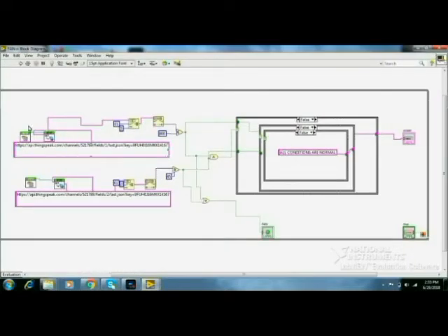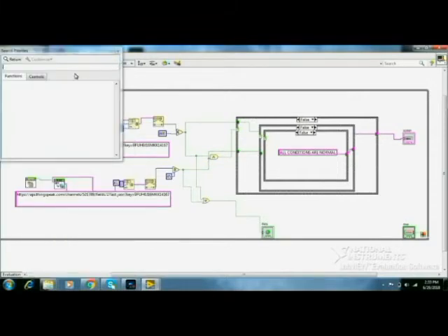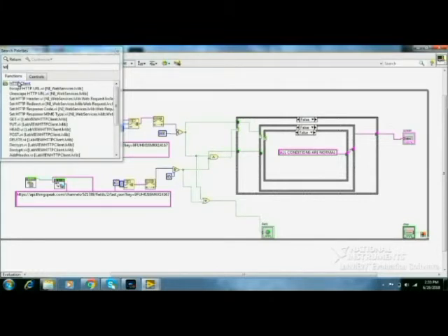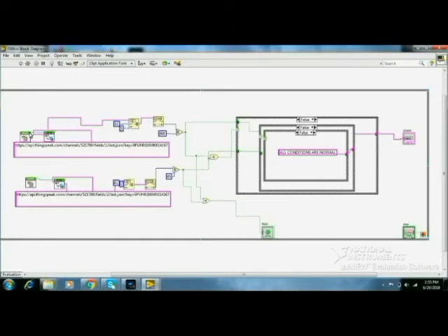As I said earlier, our mathematical model works by taking the value in the cloud. We use ThingSpeak to store the sensor value. We can retrieve data from ThingSpeak by using HTTP methods. In LabVIEW, we have the HTTP client VI palette. It is a built-in VI palette which has many sub-VIs like OpenHandle VI, GetVI, etc. For establishing an HTTP request, we use the OpenHandle VI and GetVI.